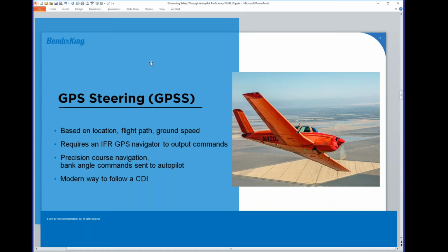One of the most impressive things about that is that when we went to WAAS, we actually started to get holds and anticipating turns, and your GPSs now had full courses that showed as you approached a turn a nice gentle curve, and all of those curves could be changed into bank angles, and then the aircraft could actually anticipate the turn and keep you on rails for the entire thing. Very, very impressive. That technology filled that gap of translating roll out of your GPS to this analog autopilot that you used to have, or that so many of you still have.